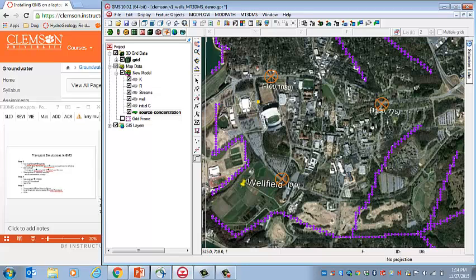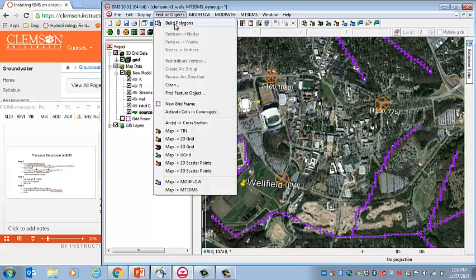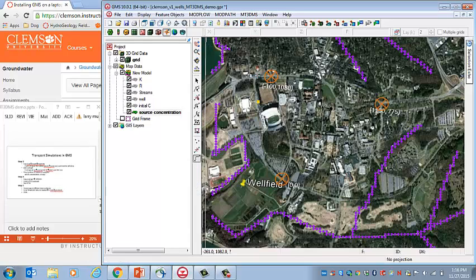And so if we were to have a source of contaminants in Brackett Hall, okay, now I'm going to put in a source that's over by the motor pool, and we'll put another one in over on the other side of campus. Over here, this is the Brooks Center, the Performing Arts Center, so we'll put one in there. Okay, so we've put those polygons in. We build the polygons like so, and then we need to specify what the concentrations are in these polygons.